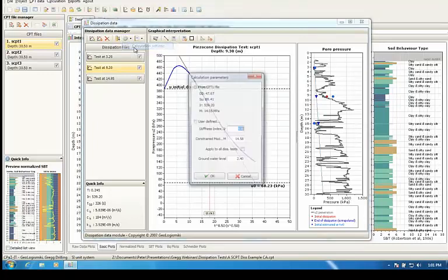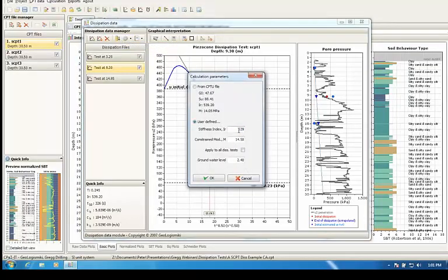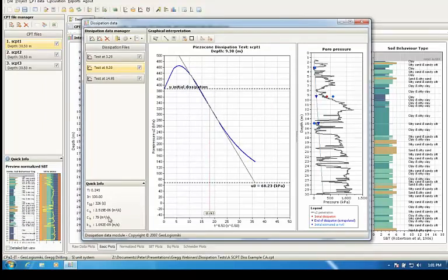Now you might think that that's maybe a little high because it is an over-consolidated clay, and from Kavvadas and Mitchell's work, it would drop a little bit with OCR. So let's just move it down to 100 and see how it changes. If you look in the bottom left-hand corner, currently it's calculating about 5.8 times 10 to the minus 6 meters per second, with a rigidity index of a little over 500. If I change it to 100, I ask it to recalculate.